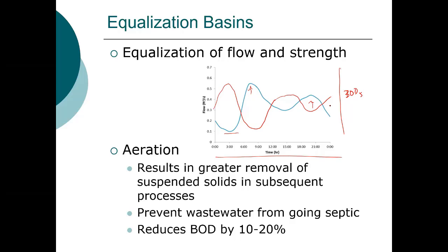It is often septic, and they had significant problems with corrosion of the aerators in this underground tank. So they actually shut off aeration because they had trouble maintaining it. And then they also had significant problems because it was this serpentine tank with sedimentation, especially in the corners.